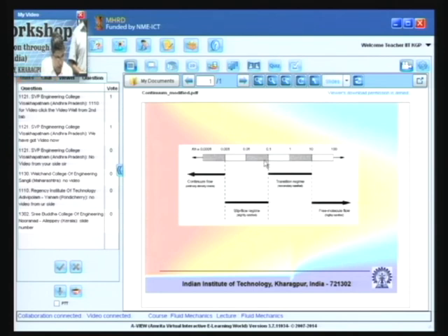And from 0.1 to 10, this is a transition region where the validity of the continuum slowly becomes weak, and the continuum approach ceases to be valid when the Knudsen number 10 is reached, beyond which we must go for analysis based on molecular dynamics, the analysis for discrete molecules. So, this is the free molecular regime.